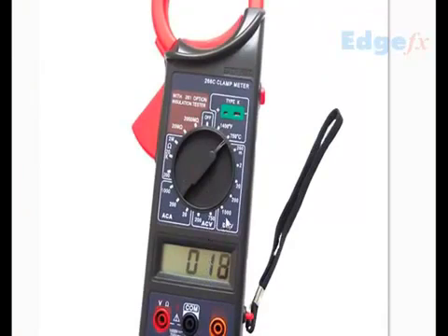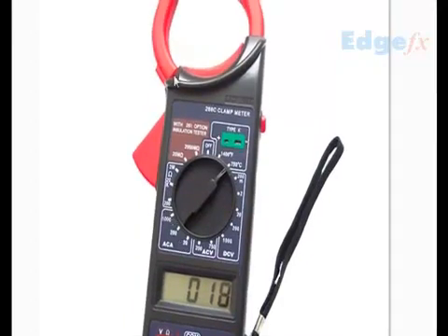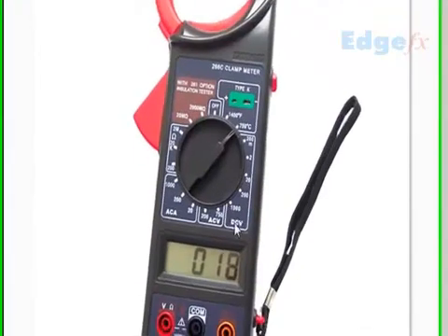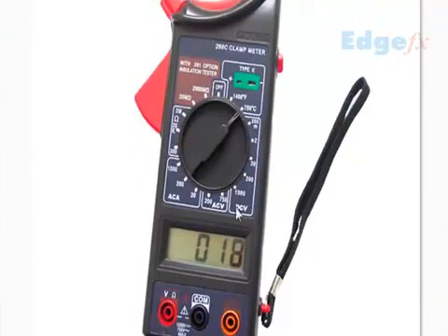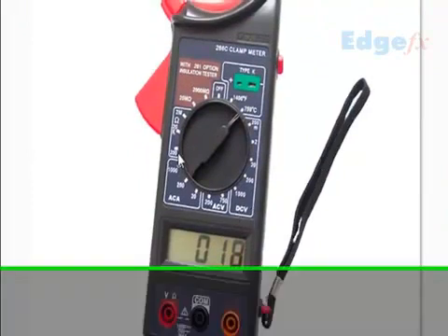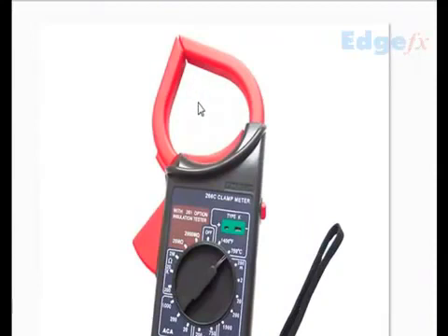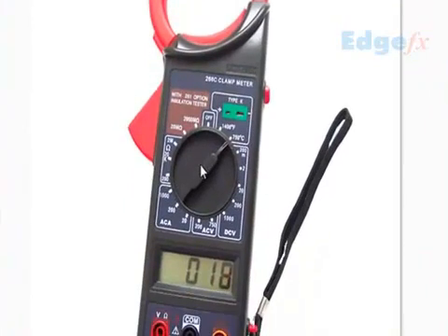It also has other provisions like DC voltage measurement, and then AC current, which of course we have to measure in this tong, that is, the clamp only. It also has resistance, certain temperature arrangements, AC voltage and DC voltage, and resistance measurement. But mostly these are used for current measurement, and that too AC current measurement. Let it be very clear, clamp testers of this cheaper type do not measure DC current. They never measure DC current.